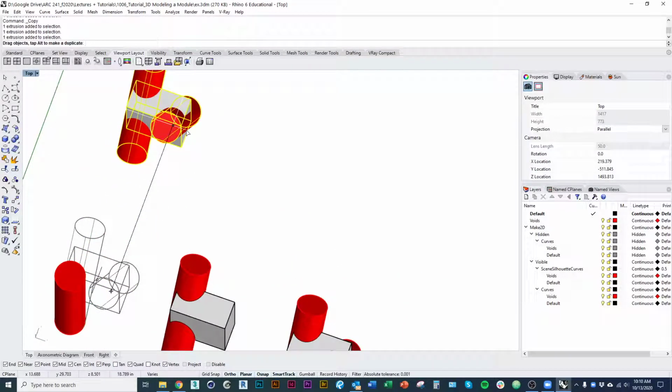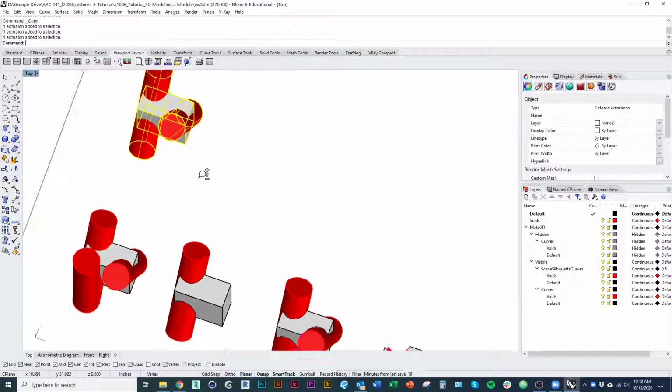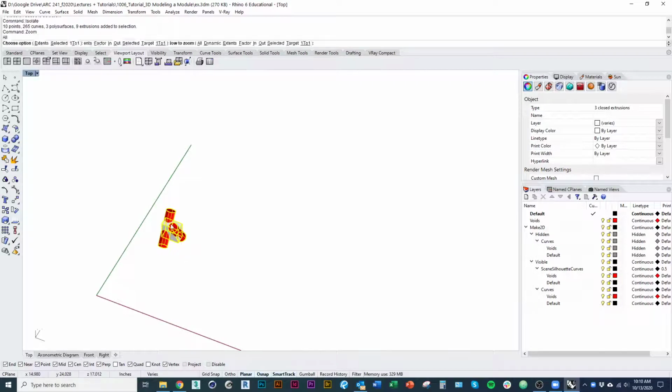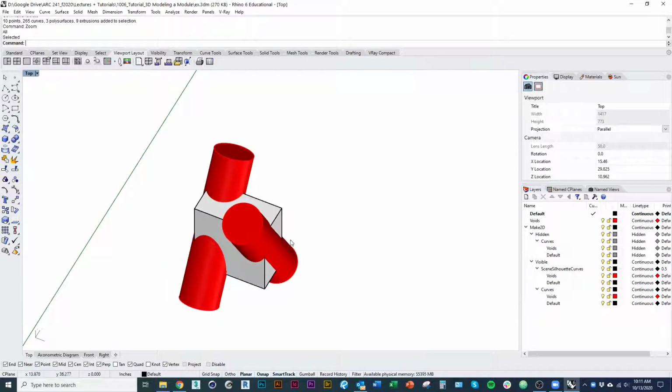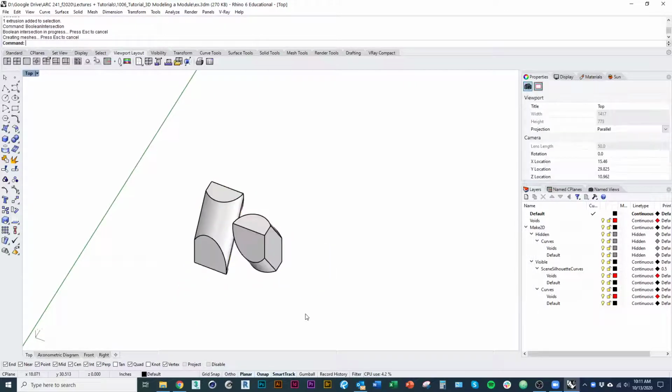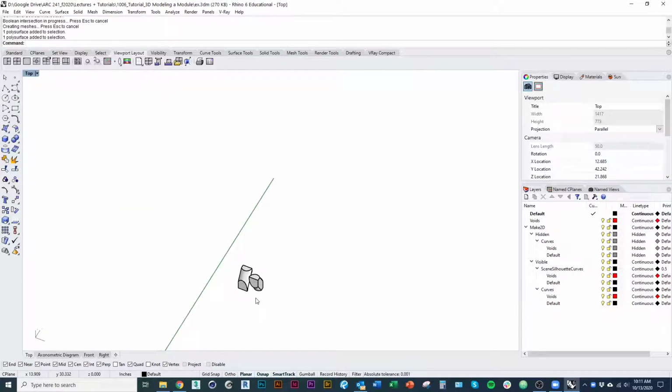So like I mentioned in the first video, what you'll want to do, isolate this real quick. Okay, what you'll want to do is do like the Boolean intersection rather than the Boolean difference to figure out what those voids should be. So you're probably going to construct a box and then fill in these voids. So I'm going to do that Boolean intersection. So those are the shapes that I would have to actually construct to insert into the box, right?